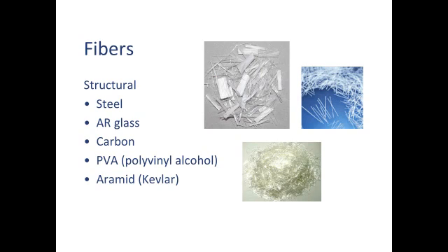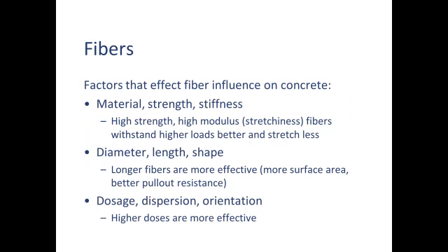Glass fibers, on the other hand, are much bigger. You always see glass fibers. The big 19 millimeter ones used for GFRC are quite visible. You can't burn them off because it's glass. But they don't stick out. They will polish beautifully, so you can polish them so you don't feel them at all. And then Kevlar's an exotic fiber that we never use. The yellow fibers, and these are some of the factors of why you would use one fiber over the other. I've touched on them.